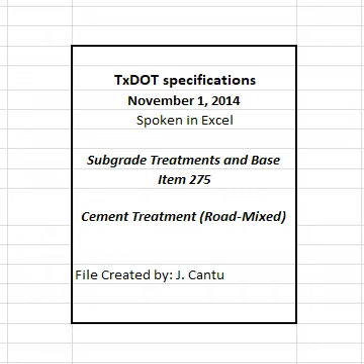4.5 Compaction. Compact the mixture in one lift using density control unless otherwise shown on the plans. Complete compaction within 2 hours after the application of water to the mixture of material and cement. Sprinkle the treated material in accordance with Item 204, Sprinkling, or aerate the treated material to adjust the moisture content during compaction so that it is within 2.0 percentage points of optimum as determined by Tex-120-E. Measure the moisture content of the material in accordance with Tex-115-E or Tex-103-E during compaction daily and report the results the same day to the engineer, unless otherwise shown on the plans or directed.